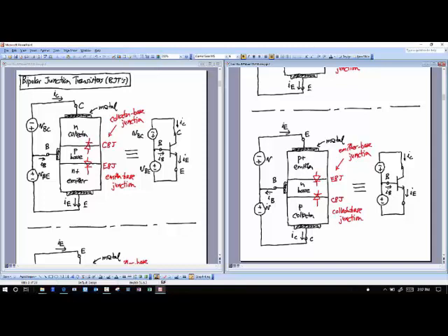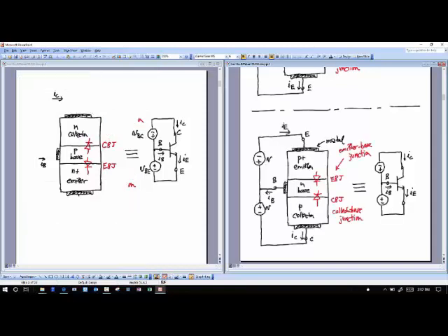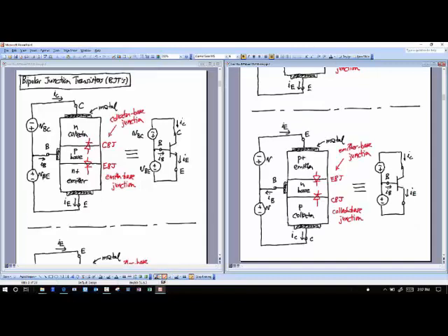So this is a good thing to do because you're basically seeing me transform this in real time from the NPN to the PNP. So you're seeing explicitly what the differences are. And so on the actual circuit diagram on this side, I guess I have to turn this voltage around and turn this voltage around. And so I'll be applying VEB here. And I'll be applying VCB here.